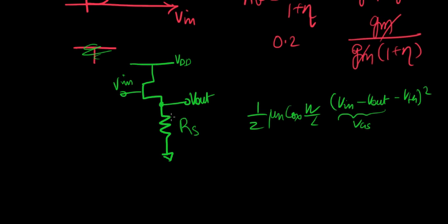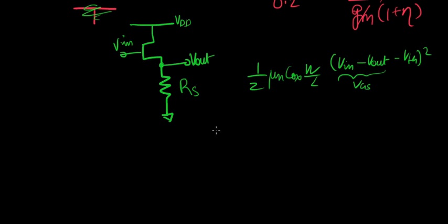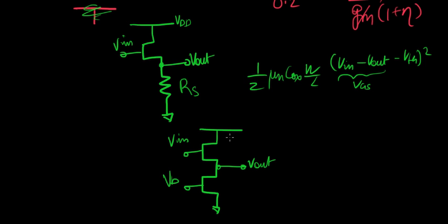So we remove the resistor from here because of nonlinearity concerns, and we replace that with another MOSFET, right? Just because it brings in a lot of nonlinearity if you use this, and also from our so many discussions before, we know that using a discrete resistor is not going to help you when you're doing integrated circuits. So that's all it is.